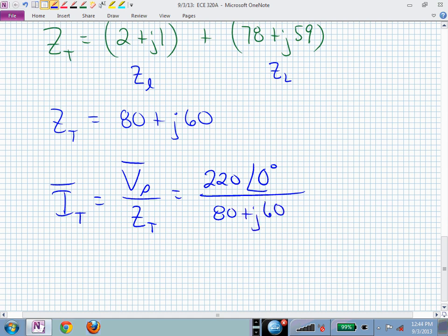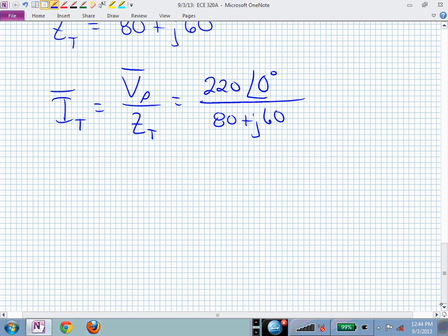It's in rectangular form, but a lot of times if I'm taking the ratio, dividing or multiplying, it might be easier to keep track of these in polar form, which allows me then to think about this impedance as also a triangle, meaning now I have this angle theta sub z, and this length is the magnitude of the impedance.